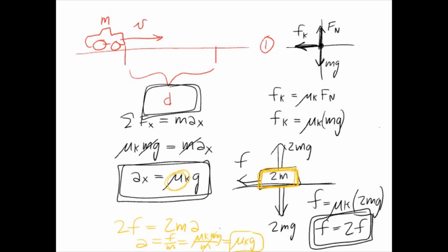But the point is, if you put your foot down on the brake hard enough, you'll have extra friction with the extra weight, and that extra friction will be just enough to balance the extra mass you have, the extra inertia of your mass, and you'll get about the same deceleration and the same stopping distance. And so again, just everyday life says that's the case, right? Because if a person's riding a motorcycle, they have the same speed limit as a pickup truck, right? A heavy pickup truck or something. And so that's why, because the pickup truck and the motorcycle should be able to stop in about the same distance. And it's going to depend mostly upon, again, that mu value.